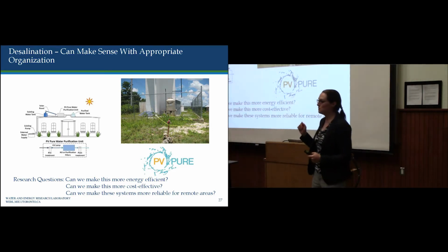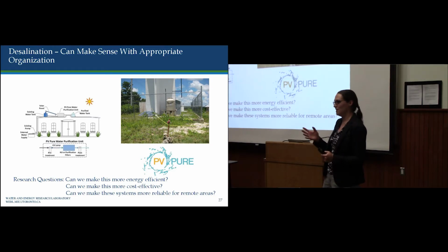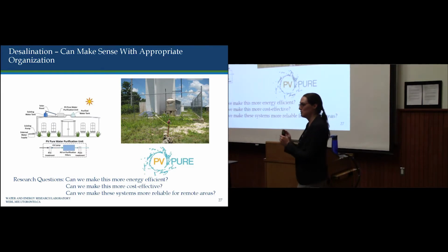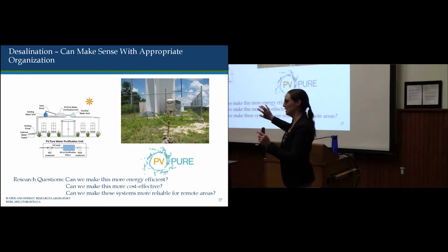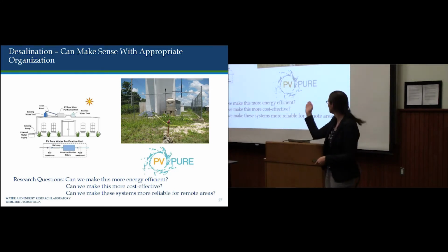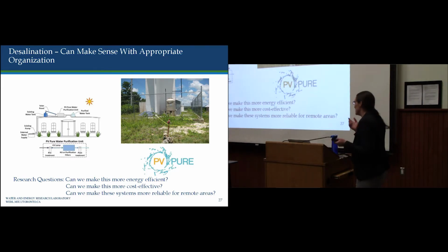So similarly for doing this, there's a measure called Gibbs free energy of the different water streams. And that's similar to the measure of salt and pepper. It's the minimum amount of energy we need to put in, based on how much that changes, to get fresh water on one side and water with extra salt on the other side. With salt and pepper shaken together, you need to put work in if you want to sort them out. This is similar, you can just quantify it in terms of thermodynamics.